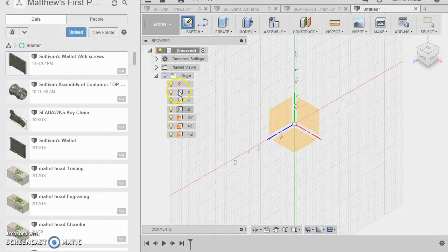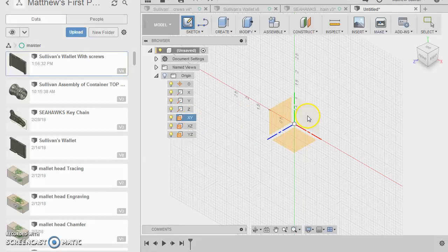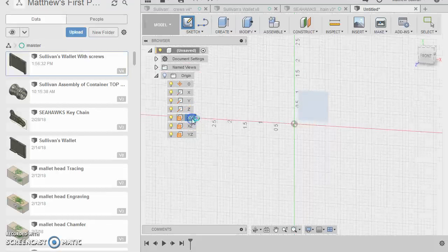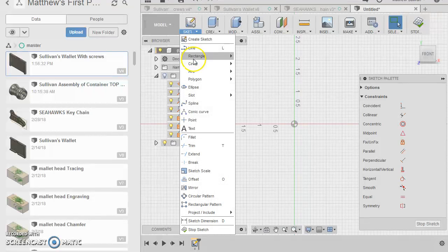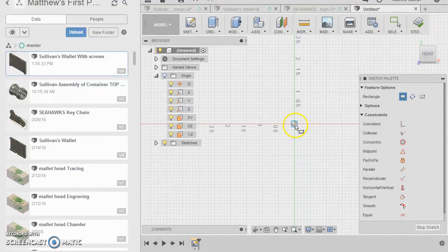I'm going to click on sketch. I was trying to drop the origin down so I can select X, Y. It's this plane we need to select. So start with this plane, start with a sketch, start with a rectangle, 2-point rectangle, and you're going to make it those sizes. So I'm going to go 2.65. I believe it was 3.975.